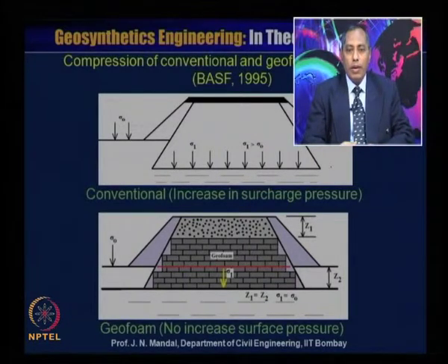On the other hand, now if we introduce this geofoam material as an alternative to the conventional filling material, as the geofoam material is a superlight material, and we are introducing this geofoam material here, and on top of the geofoam is the filling material whose depth is Z1, and here the thickness of the geofoam material is Z2 and sigma 0 is the stress, and when we apply load here you can see this is sigma 1, the development of stress at this level. So here sigma 1 is equal to sigma 0.